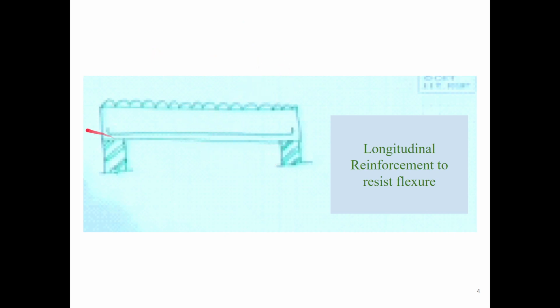The rebar is not completely equipped to resist that shear component; it may or may not, there is no guarantee. So it is important to check whether the design is capable of resisting shear, otherwise there will be chances of failure due to sliding of sections. Shear is basically nothing but sliding.